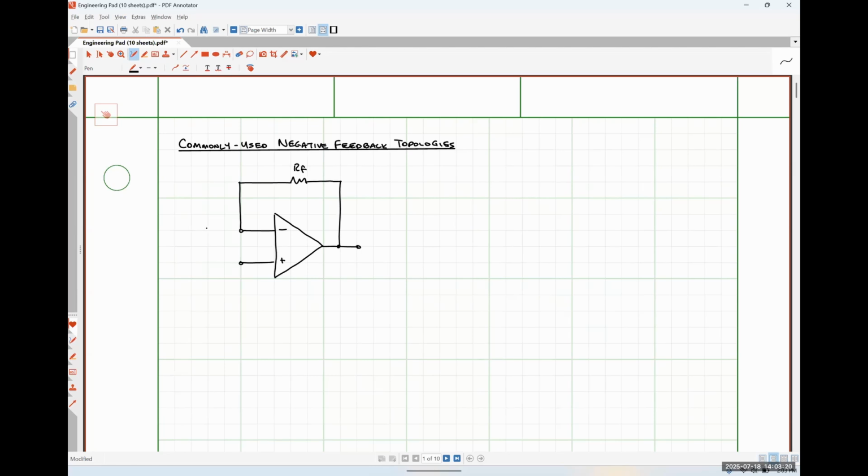I'm going to put a resistor, let's call it R1, here, connected to the inverting input terminal, and I'm going to ground the other side of this resistor R1. I'm going to apply some input voltage Vn of t at my non-inverting input terminal, and I'm going to take my output here at the output terminal.